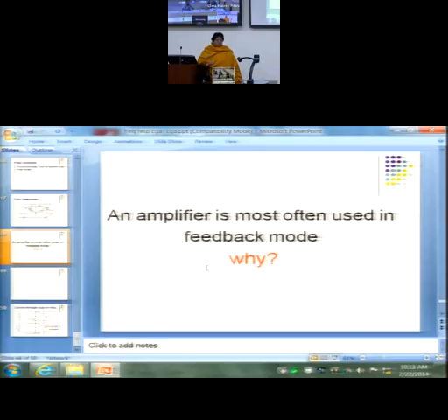That is why we configure inverting amplifiers or non-inverting amplifiers, where we say that the gain is given as minus RF by RI. Where RF and RI I configure 10K by 1K gives me a gain of 10. Then somebody will say, why are you using A then? Why use a very high gain amplifier? You are wasting resources. You are using an op-amp whose gain is 1000, 10,000 to get a gain of 10.